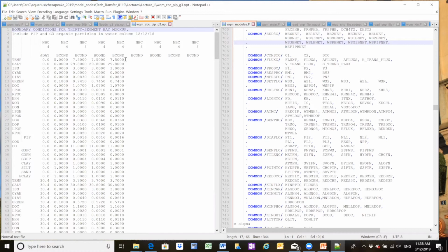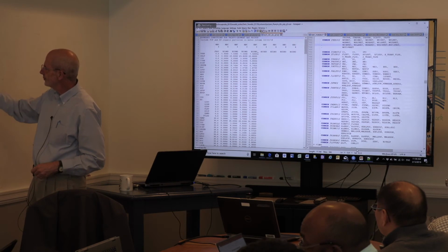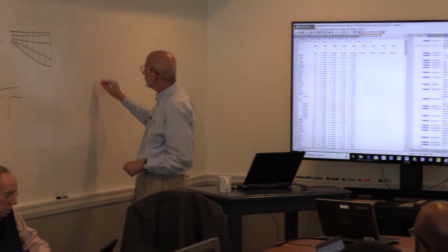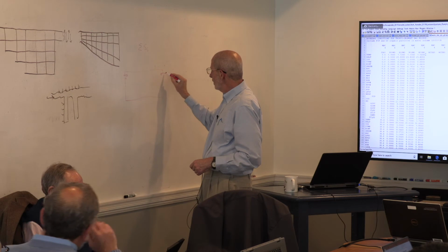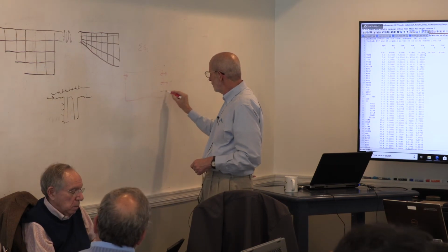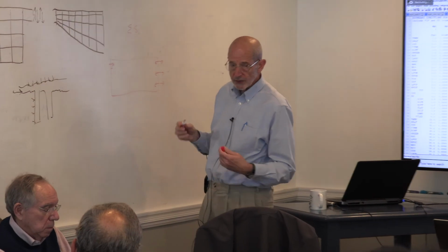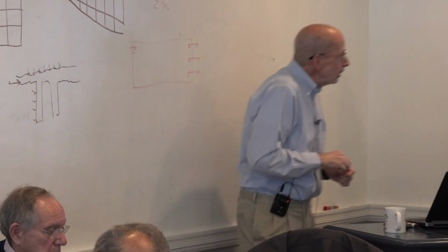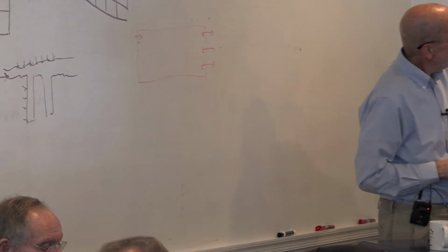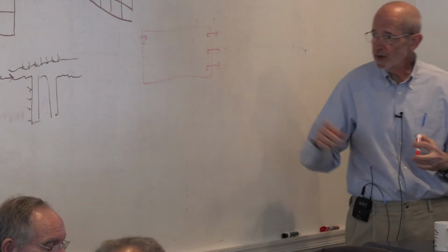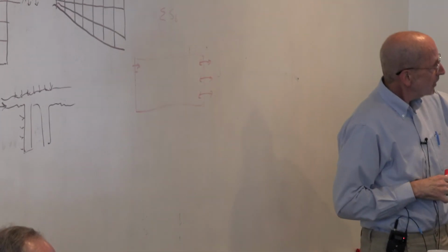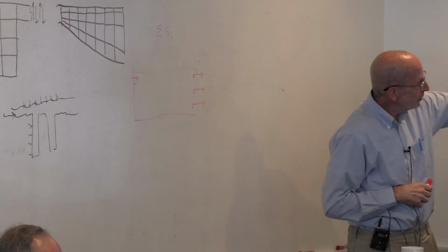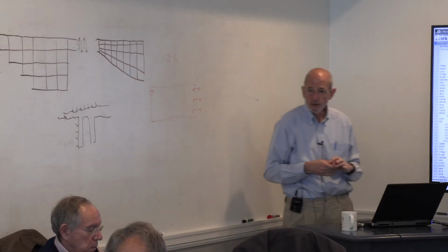Temperature, for example. Let's start with temperature. Remember our 30 box model. We had 1 open boundary here, which was the Susquehanna River, and we had 3 here, which were the ocean. That's our total of 4. For temperature, you'll see that we specify 1, 2, 3, 4 boundary conditions, so we specify temperature at all of these open faces. For salinity, it's not so obvious, but we specify 4 of them. The salinity in the Susquehanna River is 0.